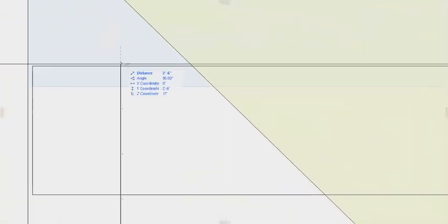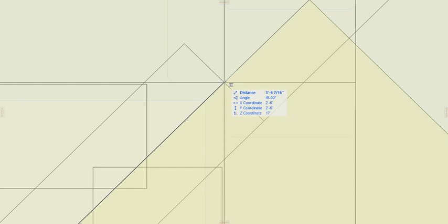One thing I'll point out here is if I go to my little 2D view and pull off of where these fascias intersect right here, and I go back to my wall, that's 30 inches. And I go back to the stud wall here, and that's 30 inches, right? But if I go from this spot right here and go back diagonally like this at the valley, it's something like 3 foot 6 and 7/16. So it's a different distance.